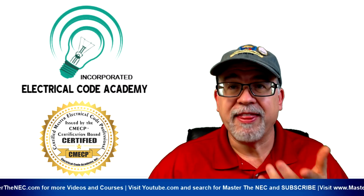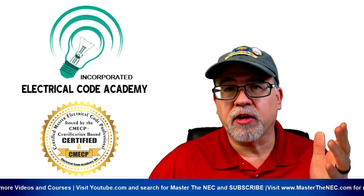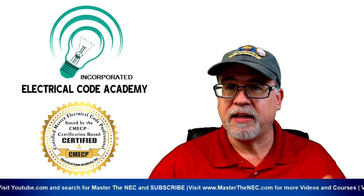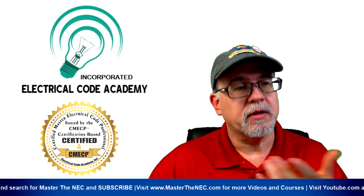All right. With that said, if they're all the same conductor size, then you can go to Informative Annex C, and that'll tell you how many you can put in. So if that's all the question is on an exam, how many 14s can I put in a trade size 1? Then the answer is 35. Okay, EMT, that is.